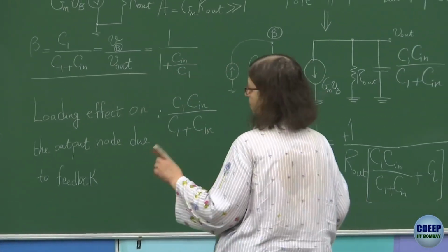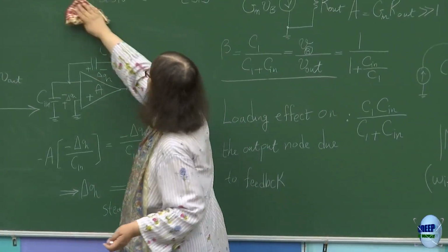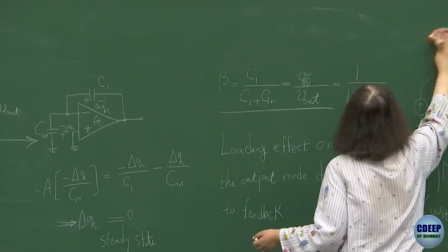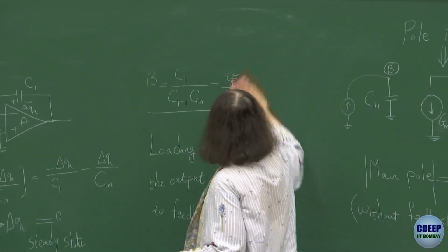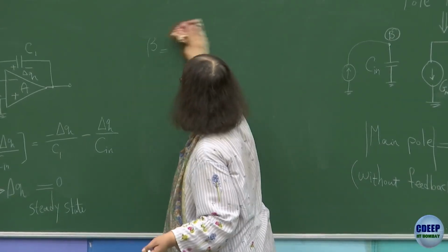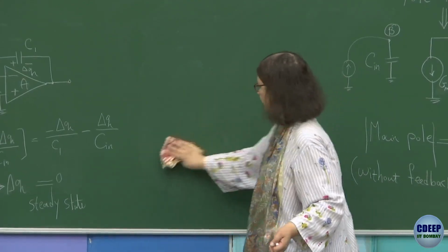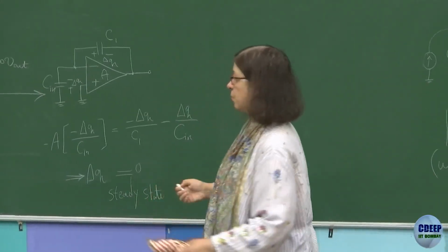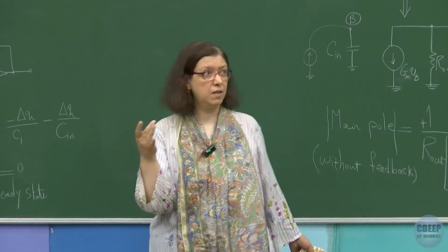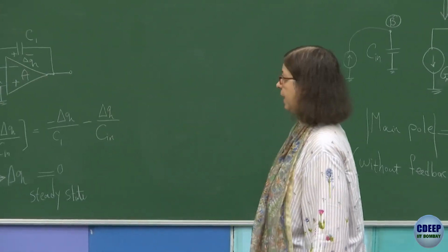In fact, we learned also how Cin is the problem for the speed of this circuit. So eventually settling time gets affected. And of course, the slew rate is a very important factor. But still settling time is important because we want to be within a fraction of LSB, say within 1/8 LSB. So in precise designs, it matters. You know that now we have so many sources of error: mismatches, variations, noise. Therefore, we cannot afford that the sampling at the discrete time itself have so much error.